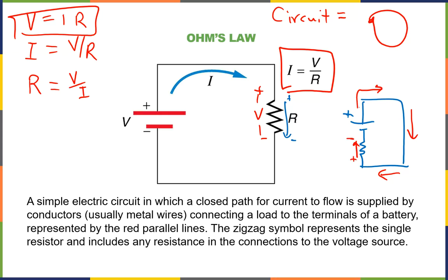Okay, so it doesn't matter which side it is so long as the flow is... The energy is dropping as the current goes through the resistor. Right. And so the positive side is the side that entered, the negative side is the side that exited. Always. Always. Okay.